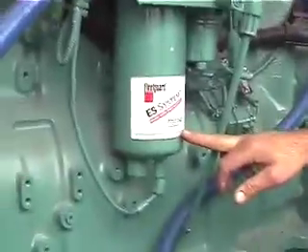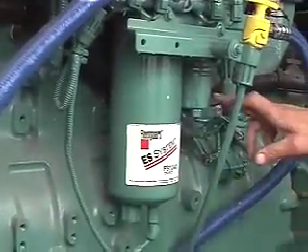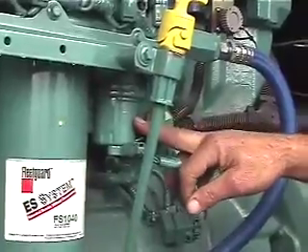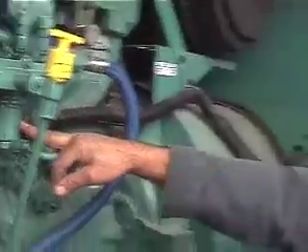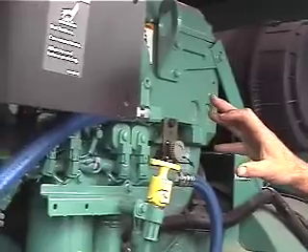So, got a fuel filter here. You got an electric fuel pump here that you'll hear when you change this fuel filter, first time you crank it, you're going to hear it go. We do not recommend for you to fill that fuel filter when you put it on. The new tolerances inside this engine are so tight, if you get any dirt inside the fuel system, then you're going to end up taking out injectors, fuel pumps, all that good happy stuff.